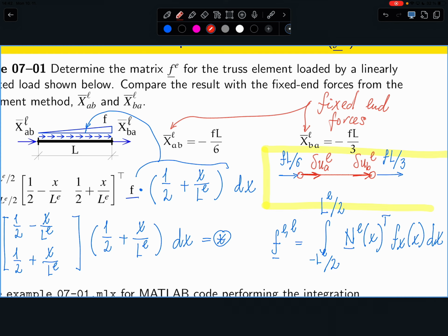So this is why these are called equivalent local forces, and again, from the perspective of the virtual work done, this cannot be distinguished from that, if you assume that the displacements in between those two extreme points are interpolated linearly.